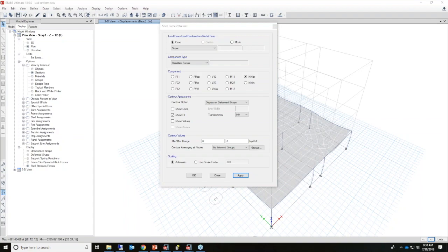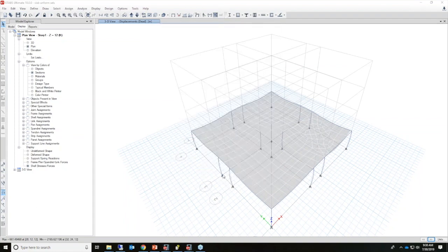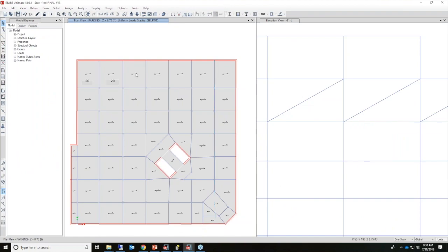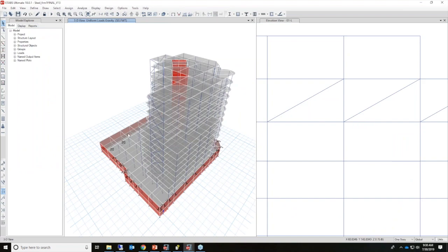Okay, how will earth pressure be put on ETABS in a retaining wall? That can be done using the non-uniform load application in ETABS that I talked about before. If I take a look at this in 3D, what I've done before is select an area object, which was a slab, but you could do the same thing for walls and retaining walls as well.